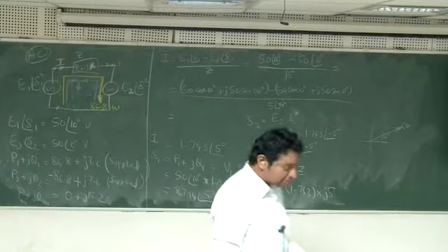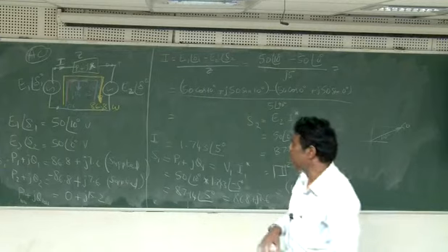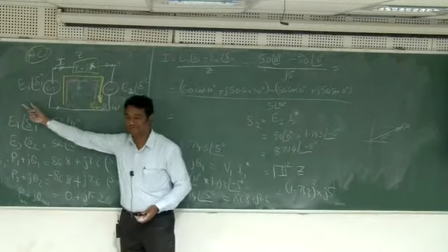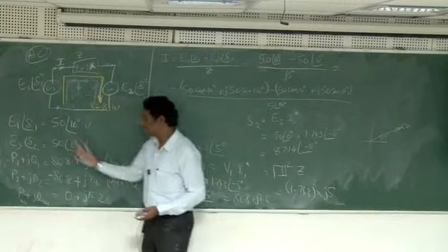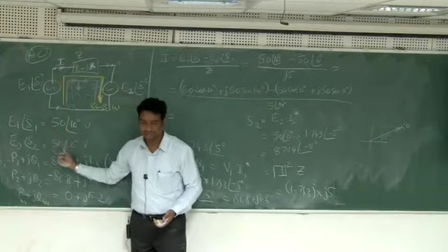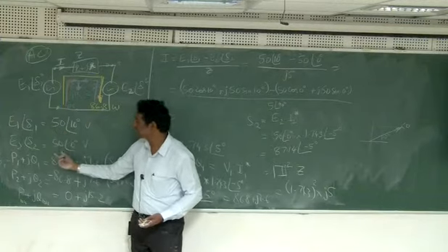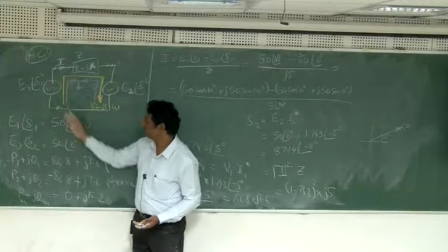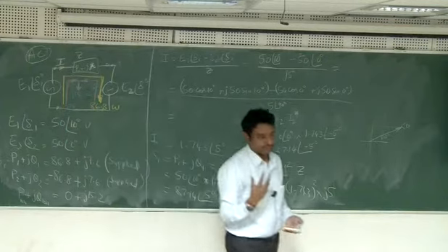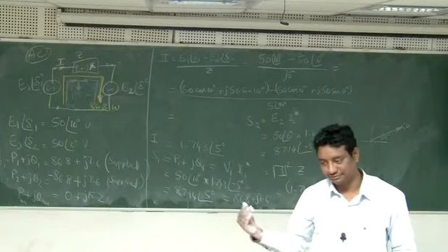Now, in the previous DC example, how to control the power flow on this line? In the case of DC, change the E1 value. Okay, but look at the E1 value here. E1 value magnitude is same. So even though the magnitude is same, what is happening? The power is still flowing from here to here because of the angles. Okay, so the angle determines the power flow.